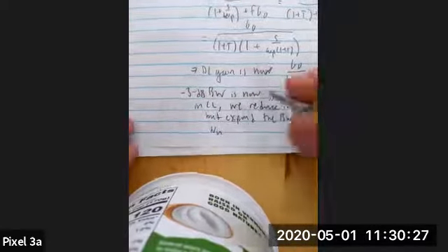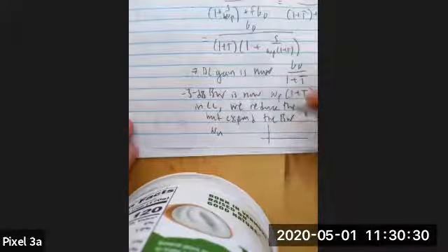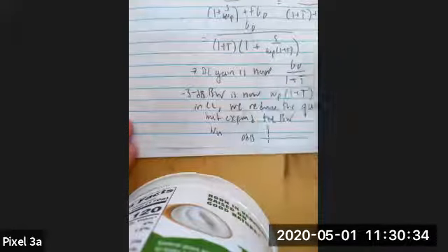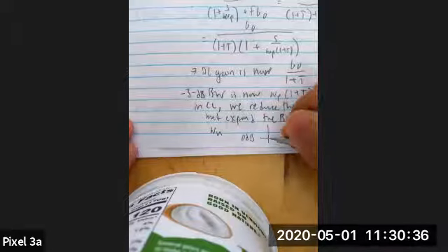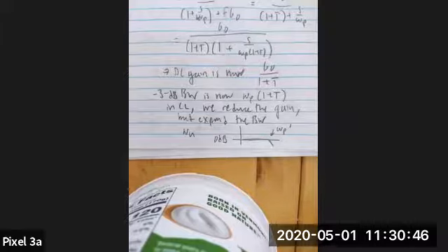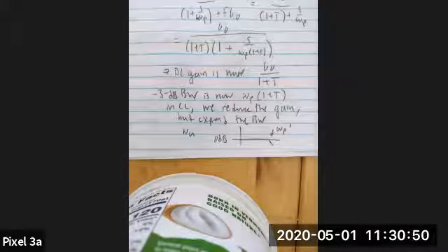So the situation that I'm referencing is that this is 0 dB, which is a gain of 1. So if we put it in feedback such that this was the case, then this new omega p that would result from the feedback would be equivalent to the unity gain frequency of the system to begin with.